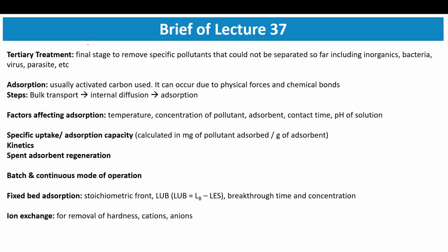Tertiary treatment is the final stage to remove specific pollutants. Specific pollutant is the important term here. These pollutants cannot be separated so far through preliminary, primary, or secondary treatment procedures. This includes some inorganics, bacteria, viruses, or parasites. So, majorly some inorganics or some microorganisms.